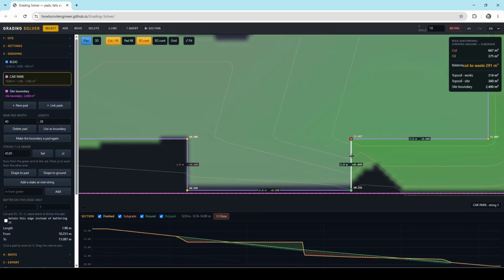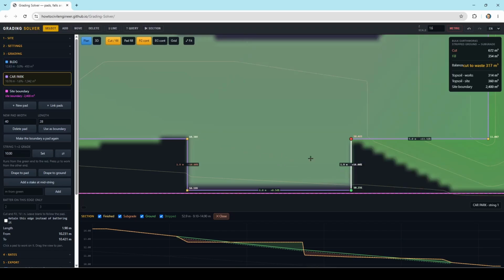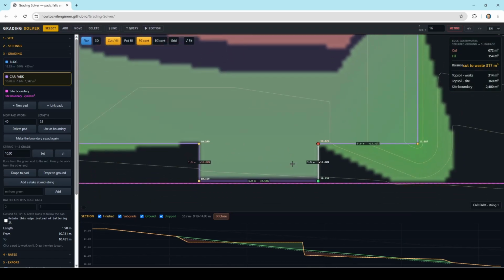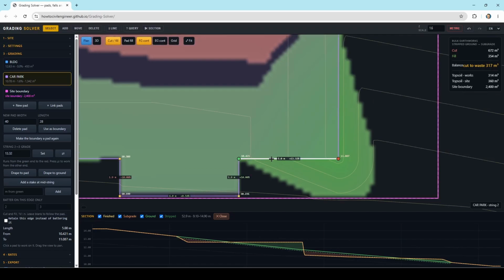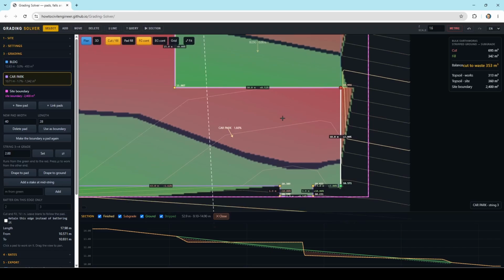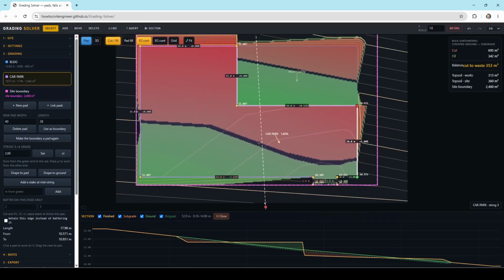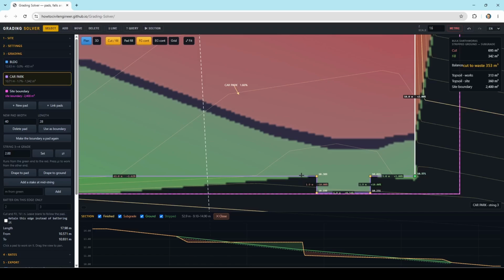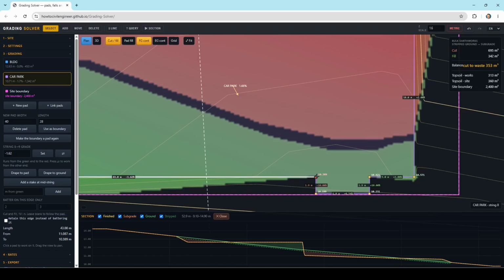and we'll do the same thing over here. I'll click on this one and set that one to 10, and that's a pretty steep ramp coming in, but we'll use that for now. And then we just work our way through here. The green means that that's the starting point, so they can be reversed. You can click on that. You can also click on the node point, click on the string, and it changes it back how it was before. We'll open the doors, they'll swing open, so 2 or 3% is not too bad, but we'll work with that for now. So if we start on this side again, you can see that's the wrong end.